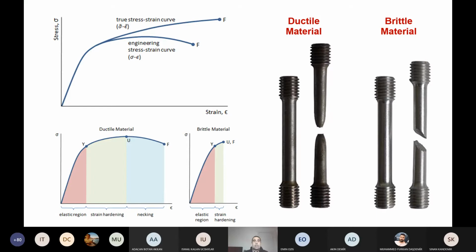I will only mention this in one sentence and not go deeper, because it's quite complicated. There's a different type of hardening, which is called kinematic hardening. That hardening occurs when you change the direction of the load, which means if you pull something and then push and then pull again and then push, during cyclic loading the material will undergo a different type of hardening, called kinematic hardening. But in metal forming, we mostly face the strain hardening phenomenon. And in very rare processes, like sheet straightening or spinning, we have to take into account the kinematic hardening behavior of the material.